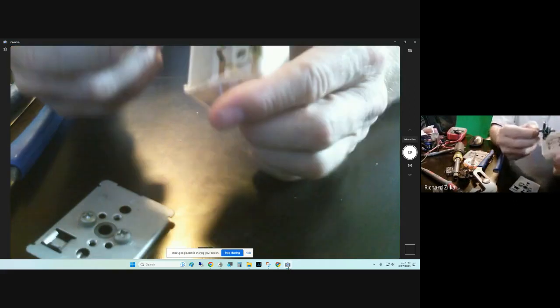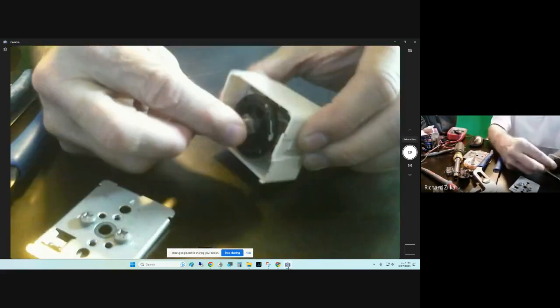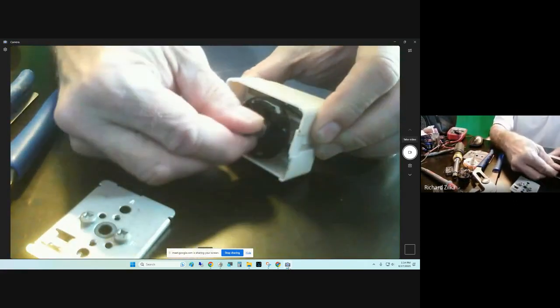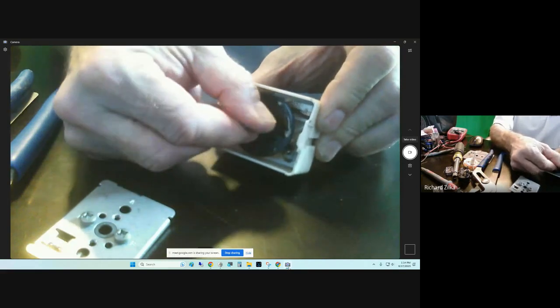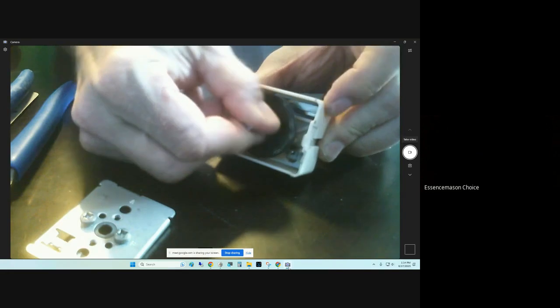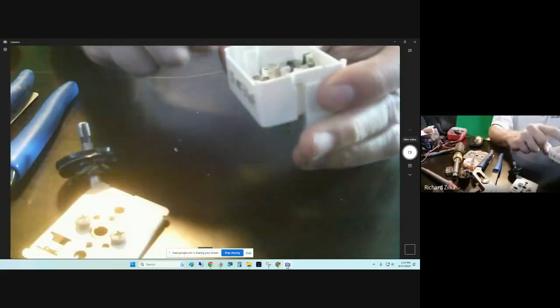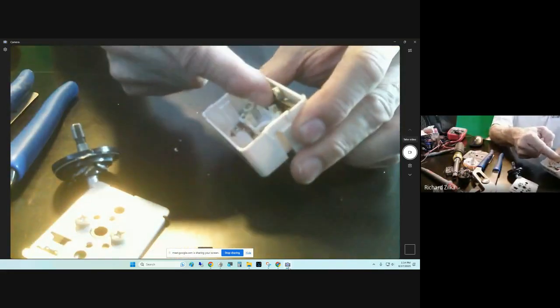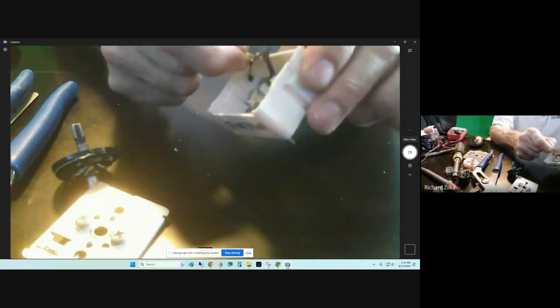So anyways, when I rotate this cam, I'm pushing. I don't know if you could see it just at the very top, but when I rotate the cam, could you see that switch going up and down? Yeah. Up here? Yes. It's going up and down. So that's the switch contact. That's the bimetal inside. I'm going to go ahead and just pull that baby open.